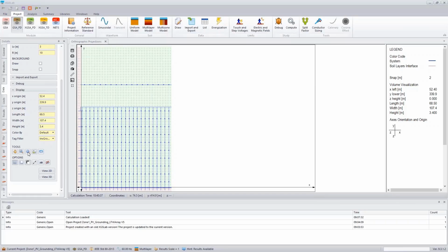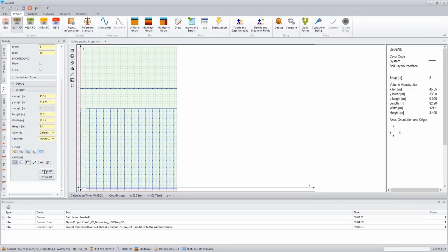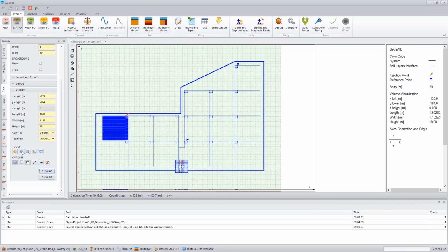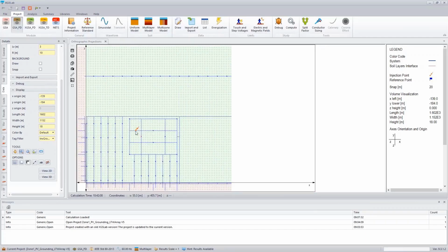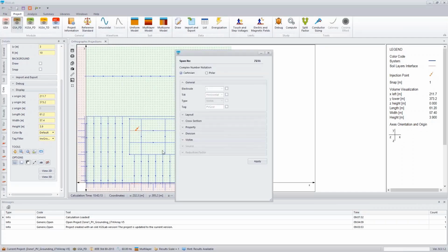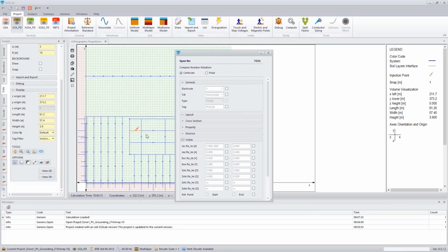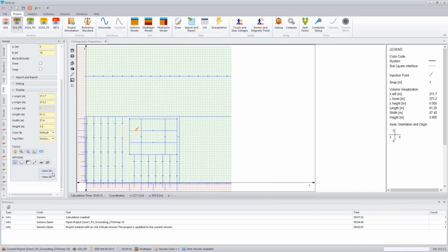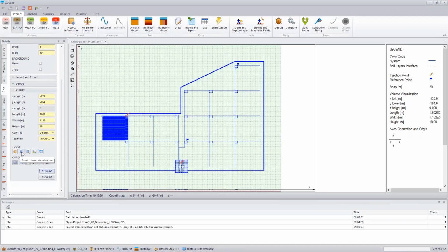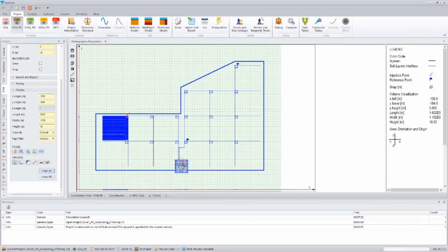high resistivity. So I'm going to go ahead and show the fault current that I injected for this system, just so people can see what that looks like in my actual model. A couple questions were brought up asking that. So I'm going into my conductor properties, and I have my, let's say, 17,000 amps that's inserted at this point if insulation or something were to fail on one of the conductors, or if personnel accidentally created a fault condition. And then at my substation, I'm pulling that out with a current that's 180 degrees out of phase with the current that I was injecting into my system.